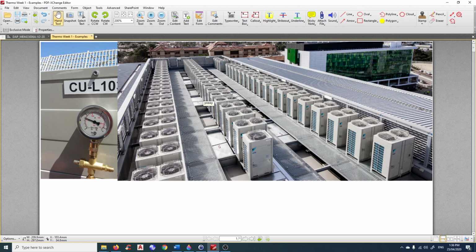Now, how is the perfect gas law relevant? Say for example, you come to pressurize this system at 7 o'clock in the morning. The subcontractor was on site at 7 o'clock. They pressurized the system, you come and witness, and you took the photo. It's about 3,800 kPa, and at 7 o'clock in the morning, it was 25-degree ambient. 48 hours later, you can't come at 7 o'clock in the morning because you have a meeting, so you come at 1 o'clock in the afternoon, just after lunch. The temperature is 37 degrees because it's summer. Then you notice when you look at the gauge, the reading is slightly different.